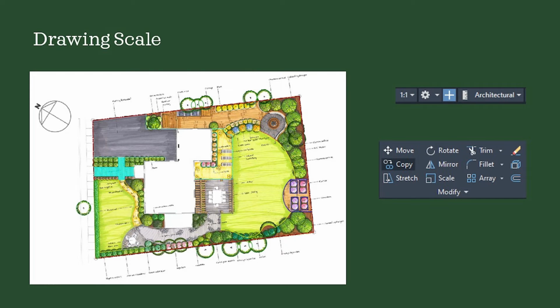The scale tools were useful in making sure we are drawing in a 1:1 scale. This is important because in model space, it is easier to work with real-world measurements rather than converting everything to the printed scale. The drawing was scaled using architectural units to keep it consistent with the real-world measurements.